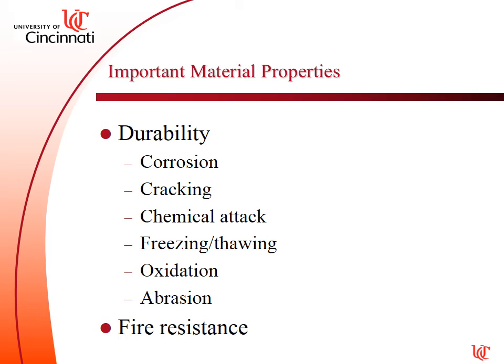What about abrasion resistance? These are all things we have to think about in terms of how our structure, how our design is actually being used. You might have a client looking at a floor slab in a warehouse, and because of their traffic flow, they're really worried about abrasion of the slab, wearing it away. So they might want a hardened slab or something of that nature.